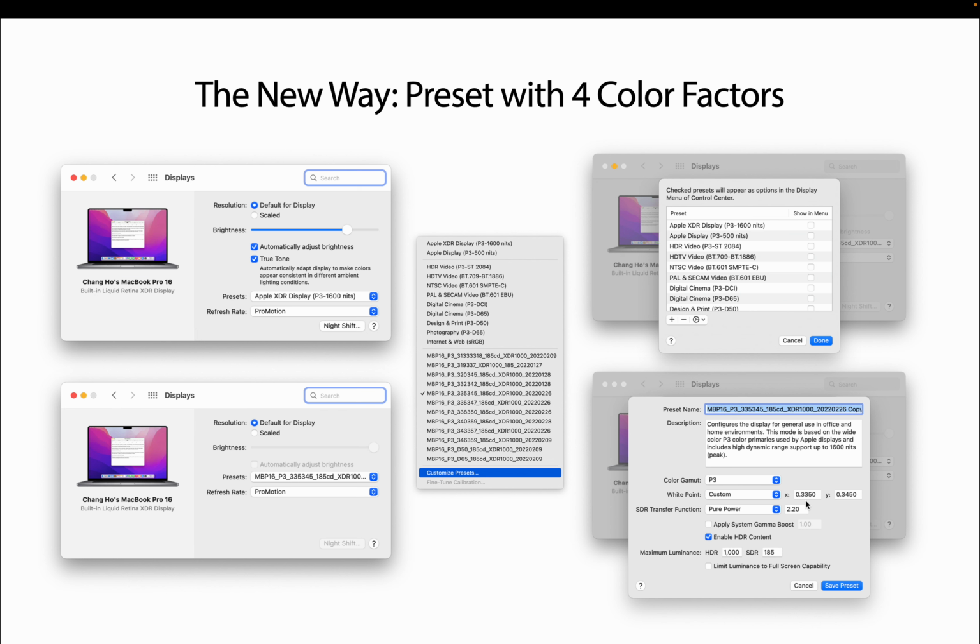If you do so, you will always get a warmer white point on display. So you must tweak a little bit, mostly smaller XY values, meaning slightly cooler white, say 300 Kelvin cooler, but it varies depending on the type of lighting. That's why I said there is no convenient way to get the right values.